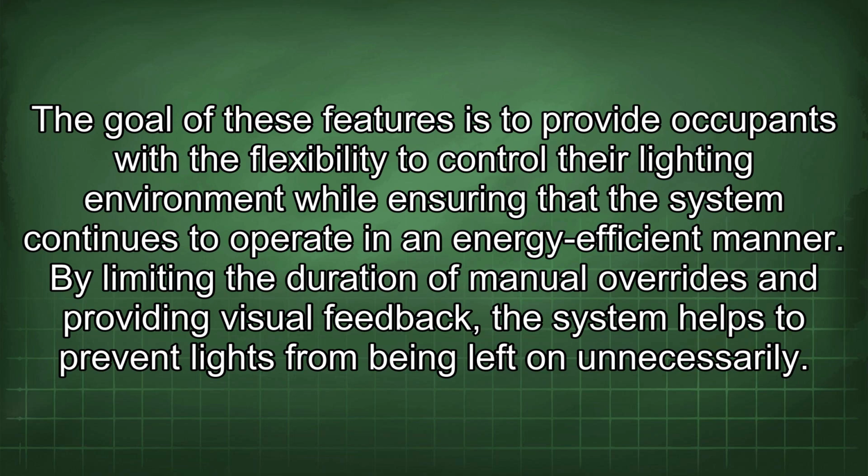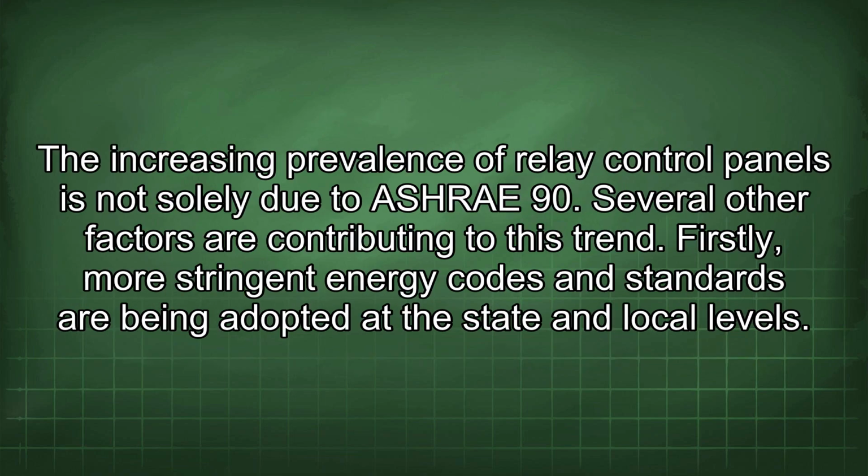The goal of these features is to provide occupants with the flexibility to control their lighting environment while ensuring that the system continues to operate in an energy-efficient manner. By limiting the duration of manual overrides and providing visual feedback, the system helps to prevent lights from being left on unnecessarily. The increasing prevalence of relay control panels is not solely due to ASHRAE 90.1. Several other factors are contributing to this trend.